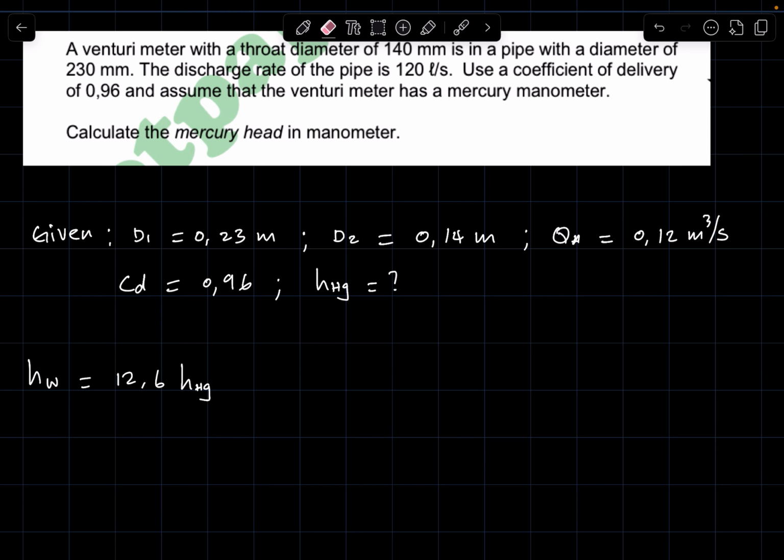Right, that's pressure energy, that is kinetic energy, and that is potential energy, aside from frictional head losses or losses in the system. Those are the three main energies that you have to look out for. With kinetic energy, we know we are going to need velocities, which we do not have here. With potential energy, we need the H's. We don't really need the H's here.